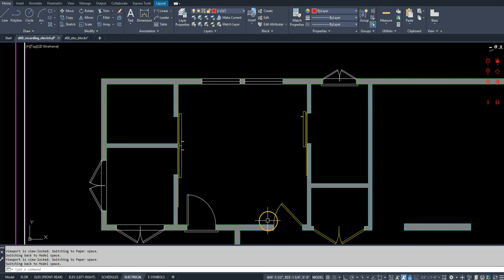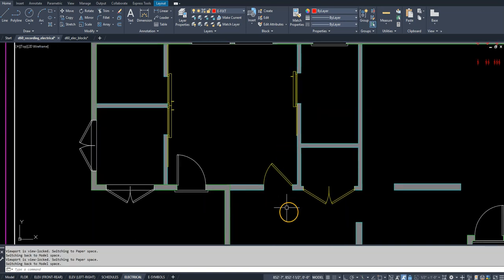For example, if I think about how I'm entering this room, the door swings this way, so ideally I would want my switches in this area here. If I come through this door from the outside, ideally I would want switches on this side of the door. So typically you want switches on the side where the knob would be if the door was closed.